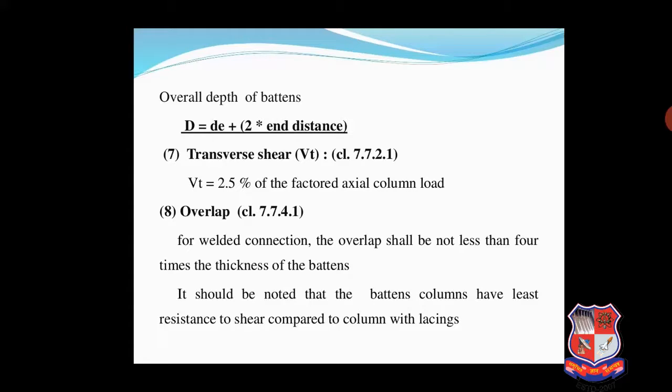Next, we find the transverse shear force VT, given in clause number 7.7.2.1. VT is equal to 2.5% of the factored axial load of the column. The same transverse shear we calculate in lacing, and the same equation can be used for battening.